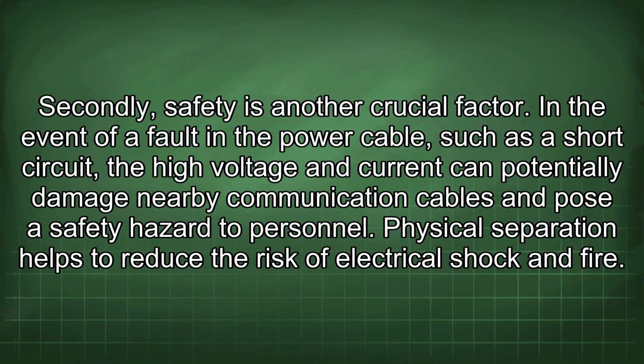Secondly, safety is another crucial factor. In the event of a fault in the power cable, such as a short circuit, the high voltage and current can potentially damage nearby communication cables and pose a safety hazard to personnel. Physical separation helps to reduce the risk of electrical shock and fire.